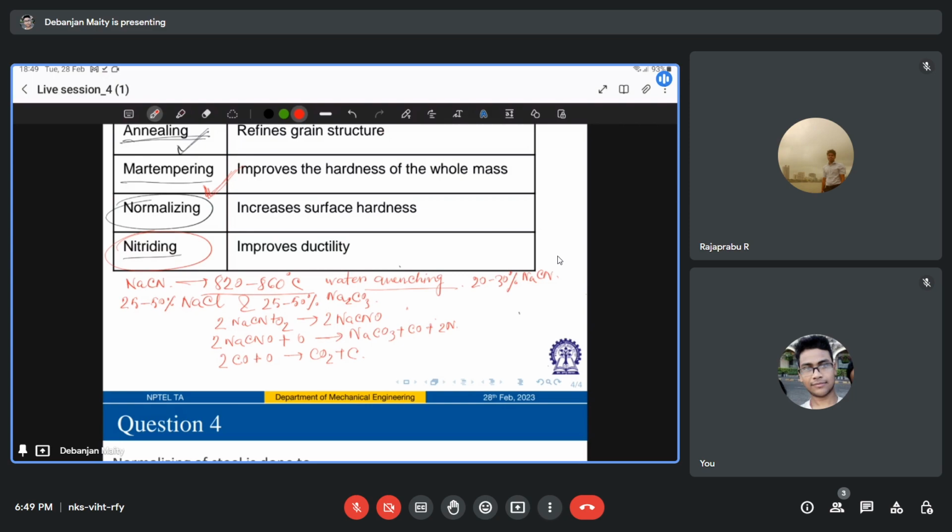and then low temperature tempering is done somewhere around 200 degrees C. The case obtained by cyaniding is of high wear resistance. So what you obtain is very high wear resistance and endurance limit compared to carburizing.